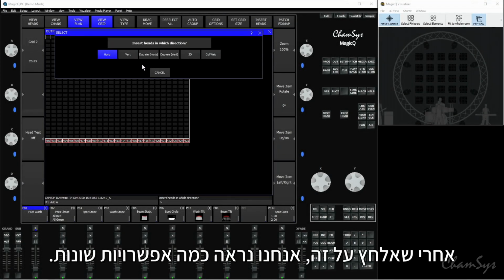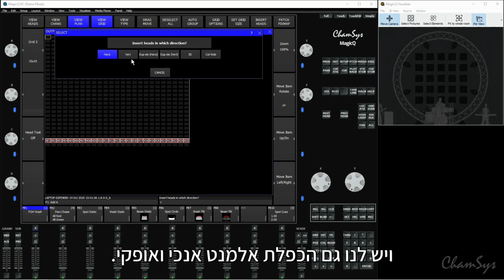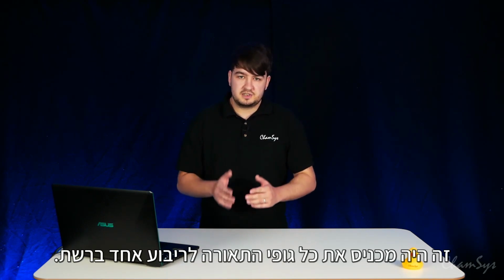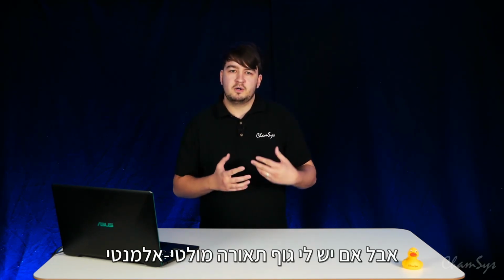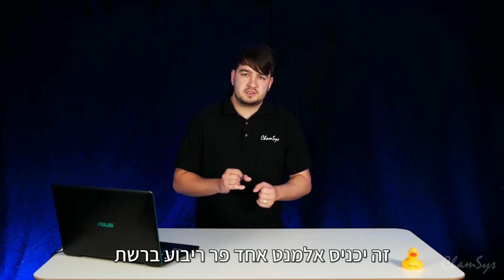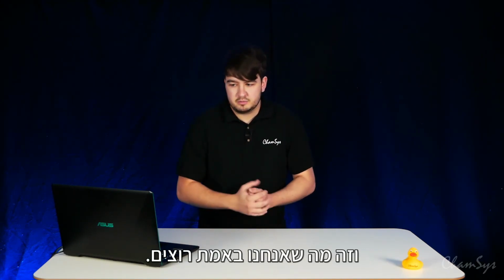Once I've clicked this, we're going to get a few different options. So we've got horizontal and vertical, and we've also got duplicate element horizontal and vertical. So the difference between this is if I was to just select horizontal or vertical, it's going to insert the whole fixture into one square on the grid. But if I've got a multi-element fixture and I select either of the duplicate element horizontal or vertical options, it's going to insert one element per section of the grid, and that's what we really want here.